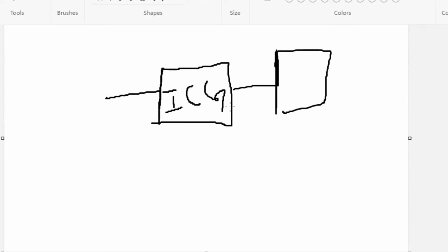What this clock gating cell does is, whenever the clock is needed only then it will give the clock, or else the clock is shut down. Meantime, only 2 pulse widths are given. If I want to give only these 2 pulse widths, I specify that I need only these 2 pulse widths so that I can save power, right? So this is one of the power reduction techniques.